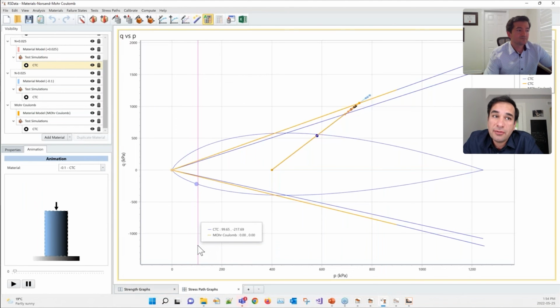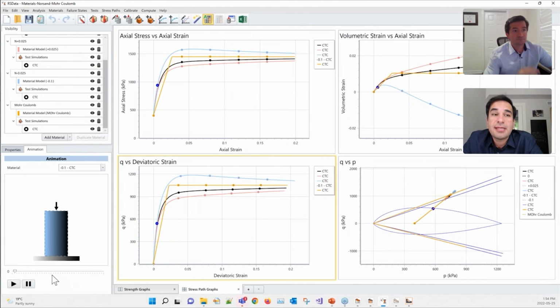And when you're dealing with a wide range of materials, such as in tailings, you should probably try testing at least 2 different gradations to see what the range may be. That's where you'll find a lot of advantages, improvements to your design. So that $5,000-$10,000 for running additional triaxial tests is probably worthwhile.